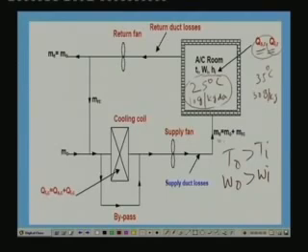In the air conditioning system, what we do is we supply, for this case for example, a supply air which is cold and dry. Okay. So, cold and dry air at the required mass flow rate is supplied to the building. This cold and dry air flows through the conditioned space, and as it flows through it, it picks up the sensible heat and the latent heat, and we assume that when it comes out of the conditioned space, its conditions will be almost the same as the conditioned space conditions.